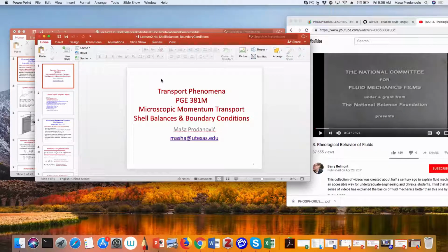So we have this, and this is one of the rare cases where I actually have an analytical solution, which is very important for any kind of engineering design. We solved for laminar flow in a tube, so that's very important. So I do have to apply that solution, I do have to have a laminar regime, otherwise the solution is not valid. And we're going to get to what we do in turbulent flow, not for a lot, we're just going to actually really mention it in passing, because turbulent flow is an entire semester course in itself.